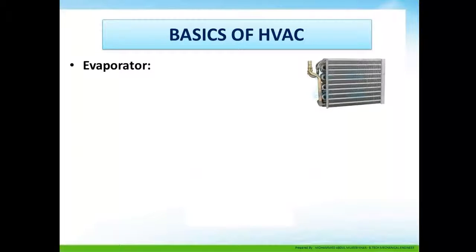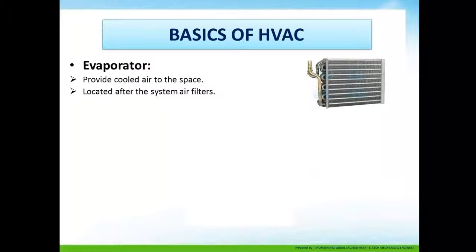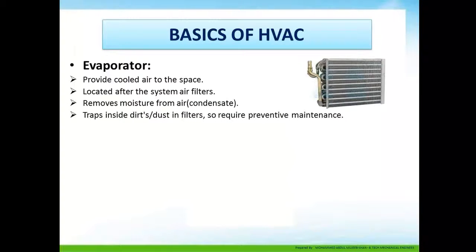Evaporator. It provides cool air to the space. It is located after the system air filters. It removes moisture from the air. It traps inside dust in filters, so it requires preventive maintenance also.